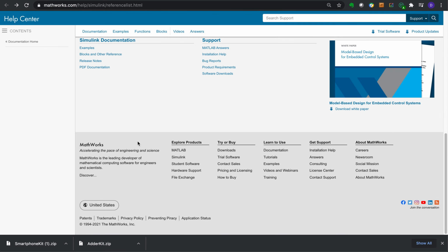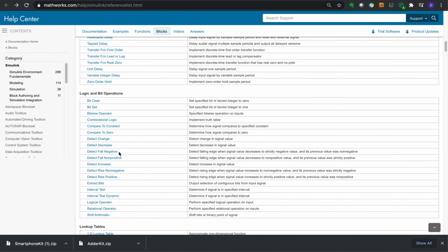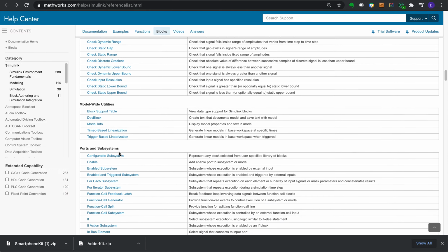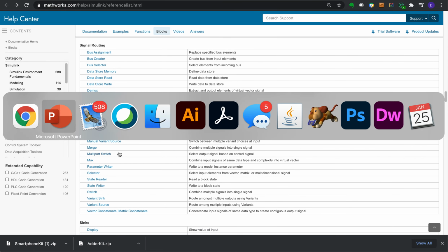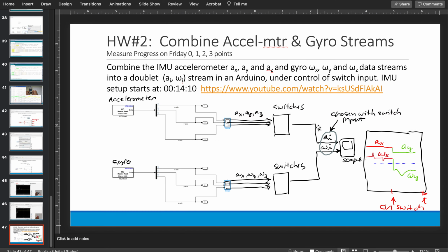And now let's take a look at something else that we need to look at. Let's review what we have as we get to signal routing. So we are looking at this device. They call this a demultiplexer. So you put data in and you get data coming out on 3 ports. The fact is, this should bother you, especially if you're a computer engineer. There's no select lines. So this is a Simulink invention, and so let's dig in and see how it works.